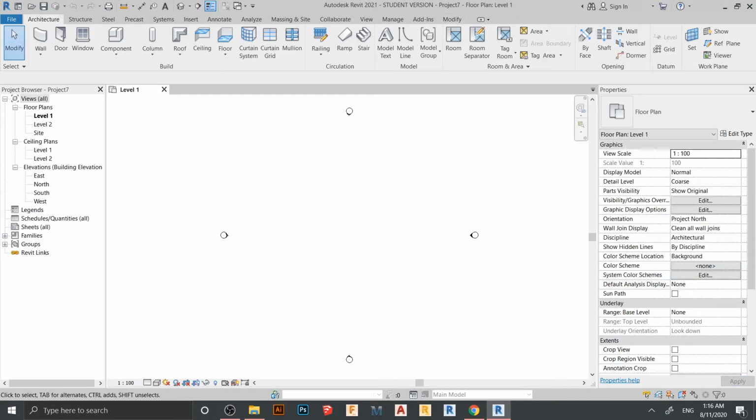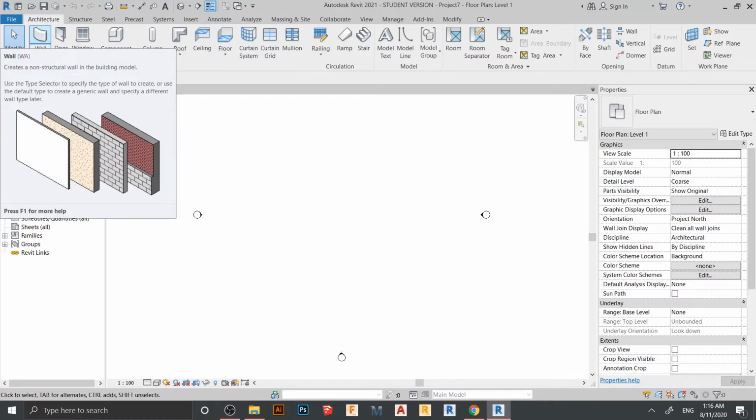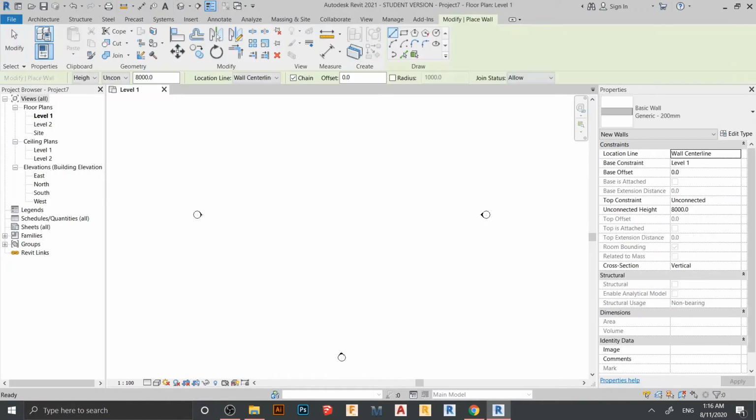Okay, everyone. Now we are in the Revit interface. Sorry, not structural, it's the architecture template. Let's place our curtain wall first before we start editing our curtain wall. In the Architecture tab here we've got Wall. When you select Wall, or you can press WA on your keyboard for the wall command, I just click here once.